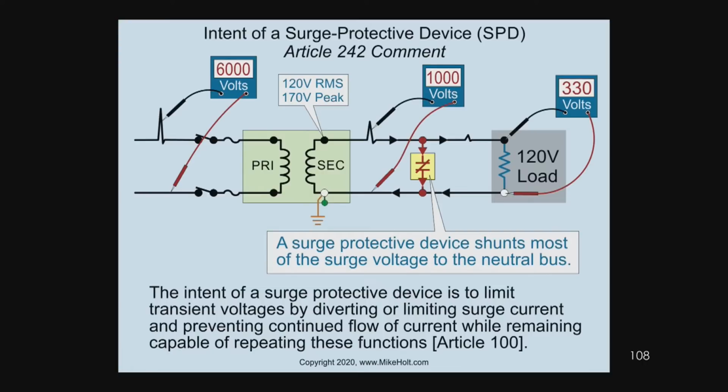Eric? Well, there's another difference, and it has to do with where the surge protection is installed. If it is installed in between the transformer and your main, it has to be a type 1. A type 2 can only be installed on the downstream side of overcurrent protection. So you have type 1 that can be installed between the utility and the main, because they realize this thing is going to have high energy. I mean, remember the available short circuit current we talked about? It comes in at 46,000 and it goes to 34,000 and 16.